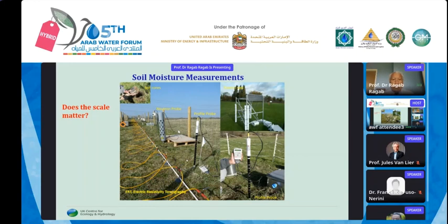For soil moisture calculations, we historically used soil cores first, and then went to the neutron probe. And then, because of the radioactive source there, we were advised to use a profile probe, which is free from a radioactive source. And then we went to ERT, or electrical resistivity tomography, where we can actually have transects of up to 64 meters. And then we went to the Cosmos system.